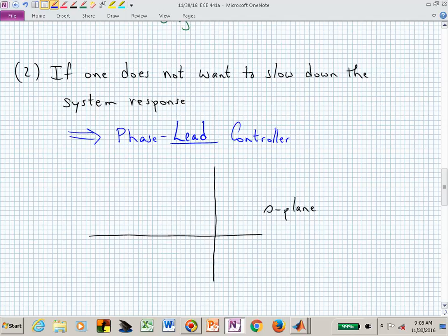We just have a first order controller. We have 1 pole and 1 zero. Where do those get located in a phase lead controller? Where in the S-plane? And now this is generic. This is just a generic relationship between the poles and zeros of your phase lead controller. How would you put those into the S-plane? First off, you have 1 of each. Where can you locate 1 singularity in the complex S-plane?